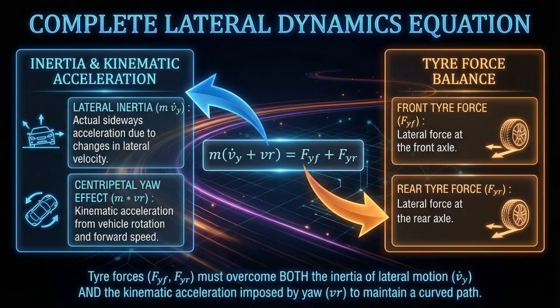Applying Newton's second law in the y direction equates the sum of lateral tire forces, Fyf plus Fyr, to mass times the composite acceleration, which is lateral acceleration plus centripetal acceleration. Rearrangement gives the second governing equation. This relation shows that any imbalance between front and rear side forces directly generates both sideways motion and yaw, explaining why steering feel and stability are inseparable phenomena.